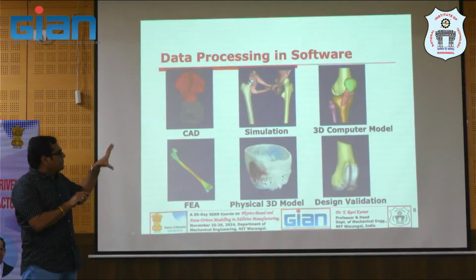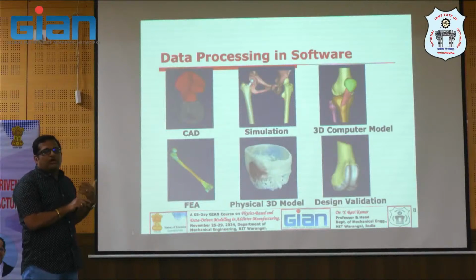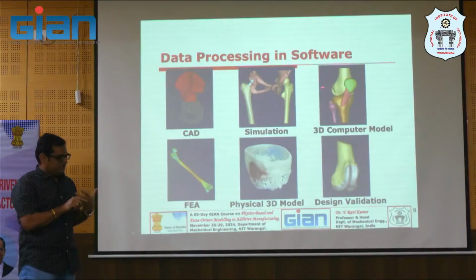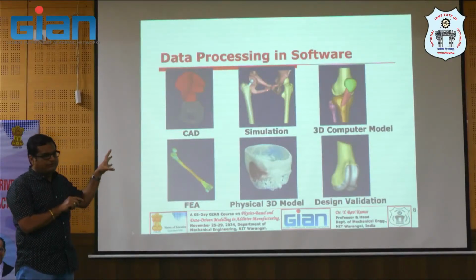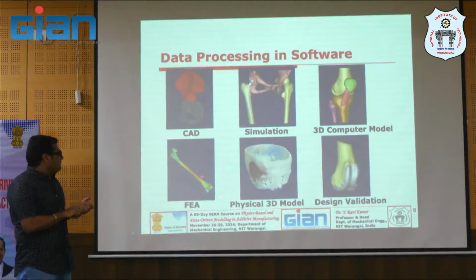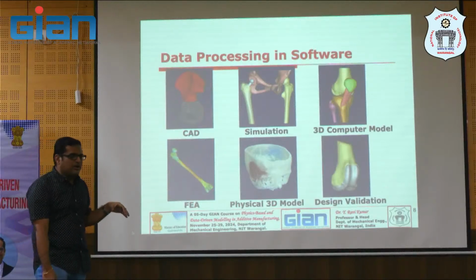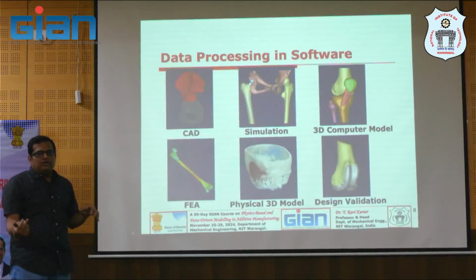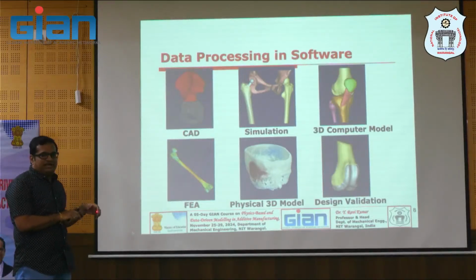You have designed by scanning the patient data, and before printing it, or before he or she goes to operate, we need to check the fitment of this joint, right? So then you can do a lot of simulation in these kinds of tools and 3D computer models. So we need to take this data into 3D, or you have designed some joint or implant where we need to test against the maximum load conditions. So maybe you have a femur bone or a tibia bone. So obviously we need to go with the FEA analysis.